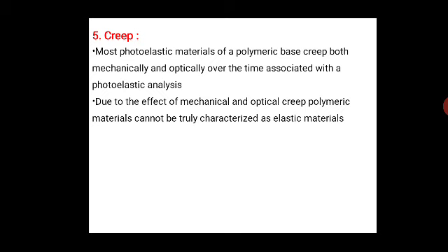Unfortunately, most photoelastic materials of polymeric base creep both mechanically and optically over the time associated with photoelastic analysis. Depending upon the timing as well as the loading, there is a deterioration or failure of the material. That is a time dependent loading.